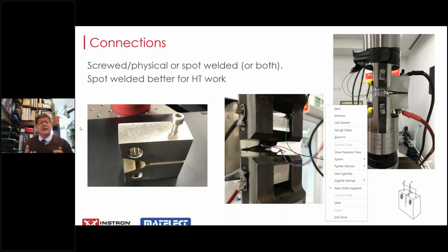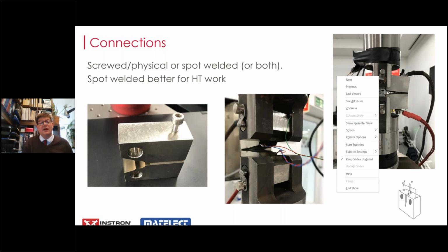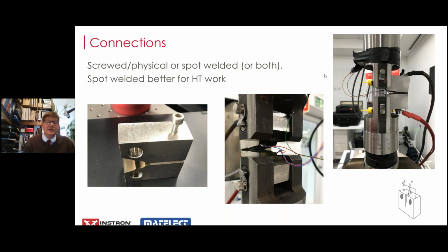The first one is to be able to get a large current through a low impedance source, because this point here is most likely to heat up if there is any resistance in the chain, because this is where the highest current density would occur. So we recommend high tension, high strength screw fastenings or spot welding of a substantial stud onto the specimen and then bolting down.